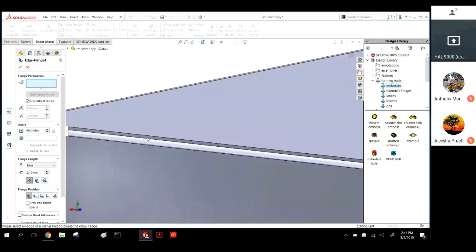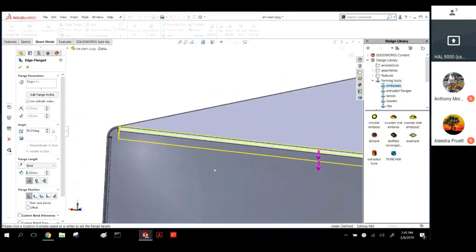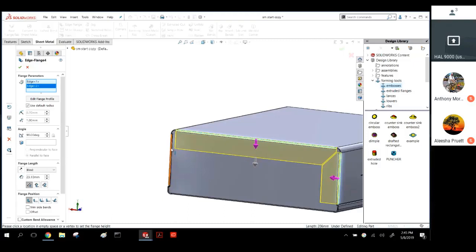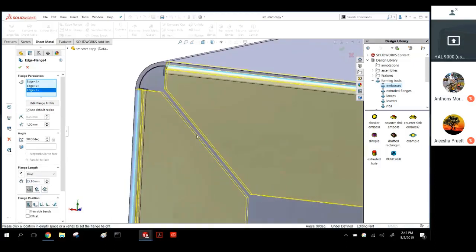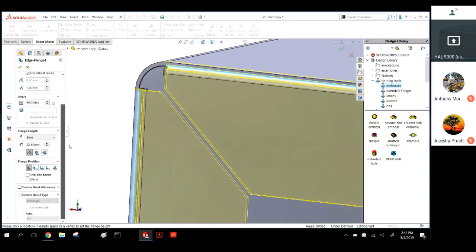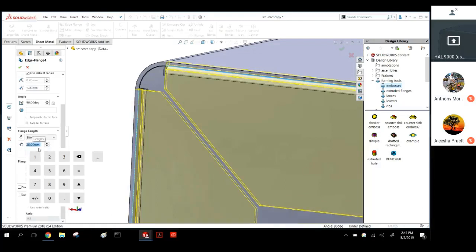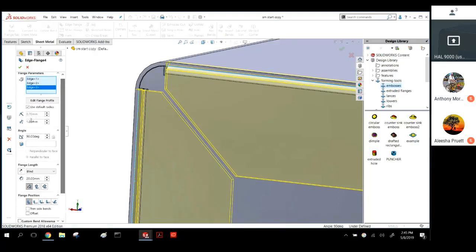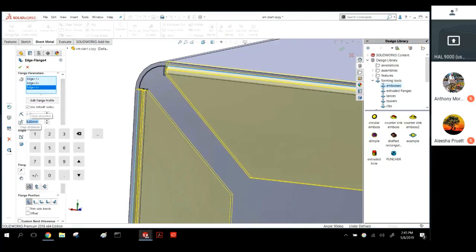When you're doing just a regular miter, that's really all you need to do. I showed you that you can do multiple edges earlier, but when you do multiple edges that run into one another, they automatically miter to themselves with this edge flange tool. All you need to do is set that, and that sets the edge flange. The other thing that you can set is the gap distance here. So that's how close those two miters come to each other.